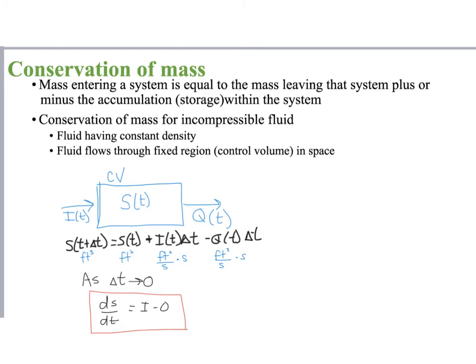And so this I is going to be all of the inflows that occur into the control volume, okay? This I, again, is all the inflows. So we have to think about all the different inflows that are happening into the control volume, and then O is all the outflow. So our job as water resource engineers is really to figure out all the outflows and all the inflows into our control volume, and then look at it over some time period.